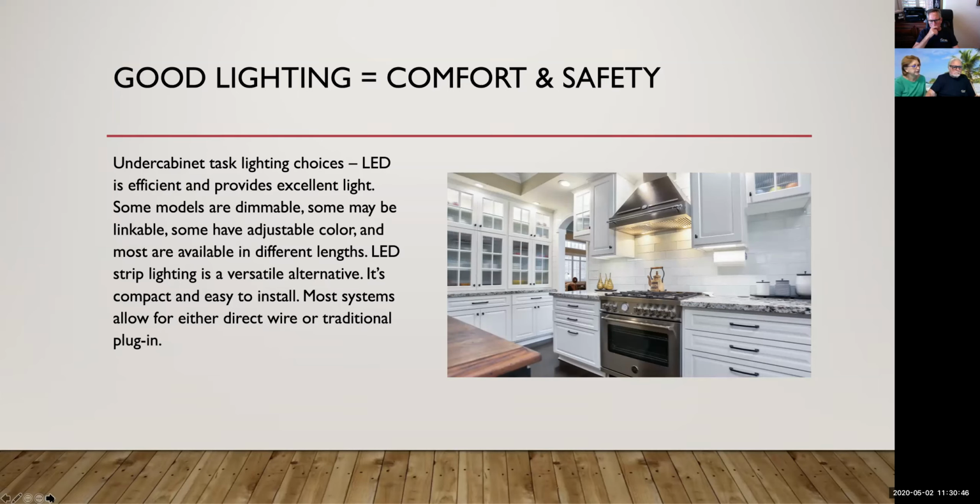Exhaust fans are required in all bathrooms, even those that contain a window. That's a reasonably new code, and the fan must be ducted to the outdoors. No, no, no, not into the attic, not into the crawl space, or through an E-vent.